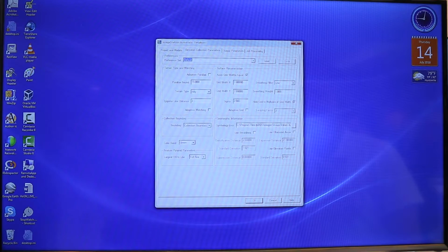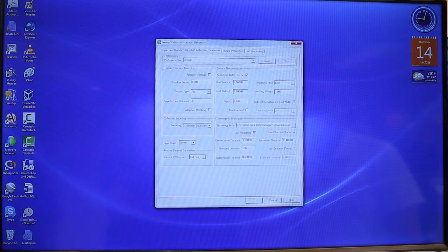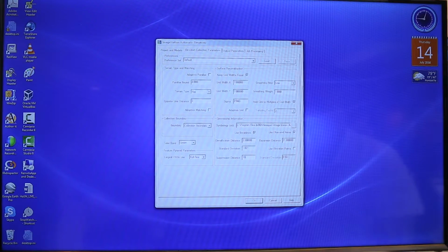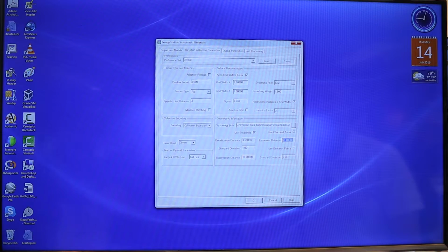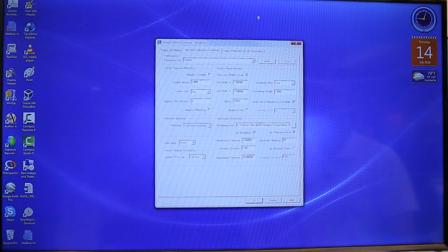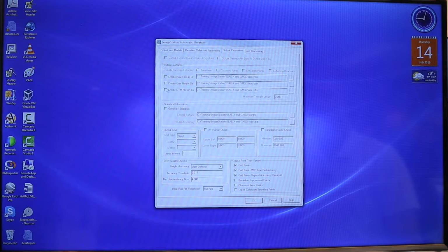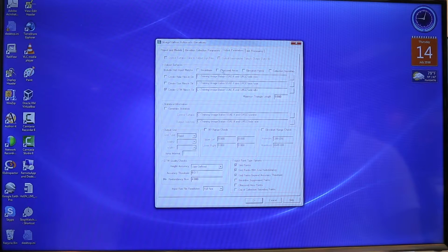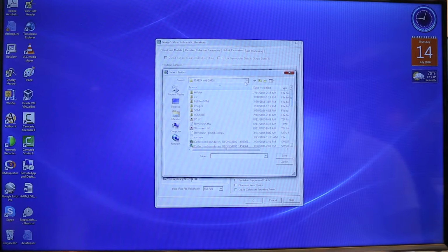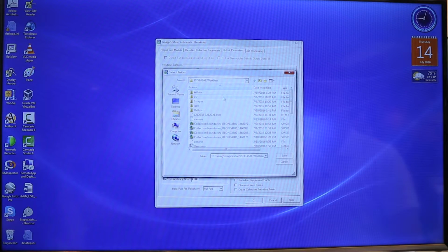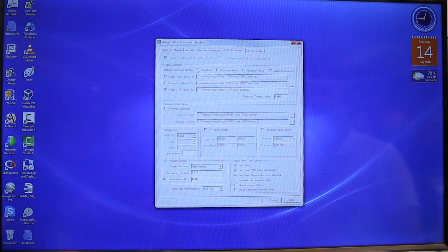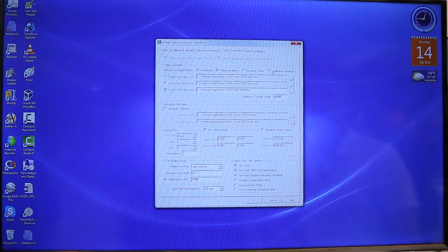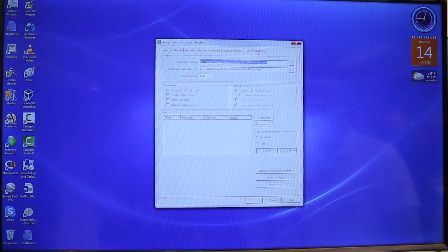Now I can set the parameters to use when processing. I'll select flat. I want to use the breaklines and obscured areas. Set the suppression distance and expansion distance. Specify output parameters. I want to create the DTM files in this folder. I want to use the breaklines, obscured areas, and collection boundary.